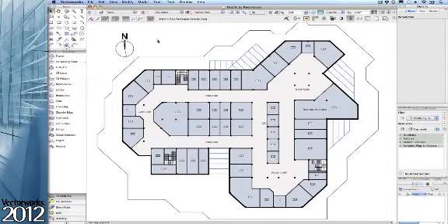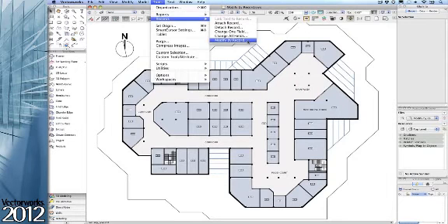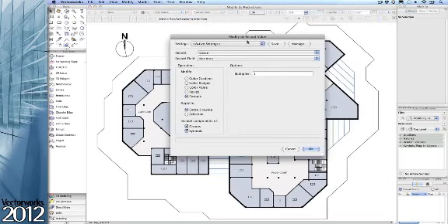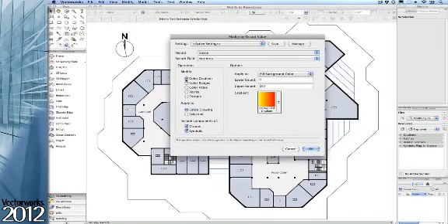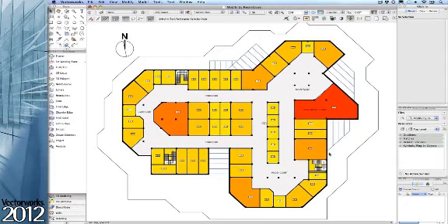Here's a wonderful new addition that will really speed up the process of making modifications on, say, a space plan. With this Modify by Record Value command, you can automatically modify the attributes of objects, resize objects, and even create extrudes from objects sharing a specific record value. In this case, we want to apply colors from a gradient based on a net area of the selected spaces in this mall floor plan. And just like that, we've done a color scheme based on space areas. Cool.